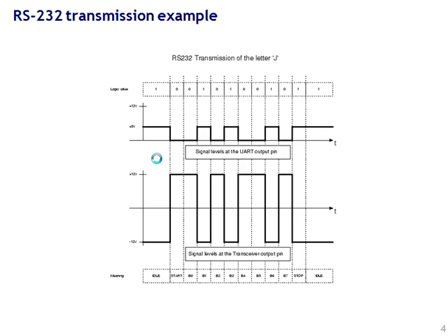A self-clocking code is a code that contains the clock. In an RS-232 transmission done in an asynchronous mode, you have what's known as a self-clocking code. Your self-clocking code gives you start bits and stop bits, and then data bits. This down here says B0, B1, B2, B3, B4, B5, B6, B7.